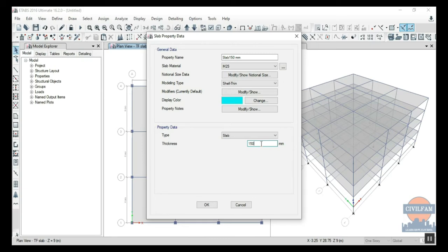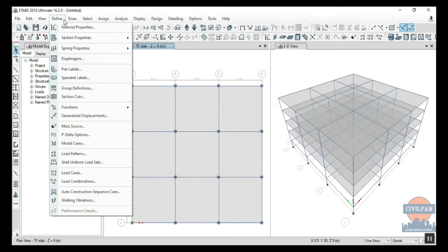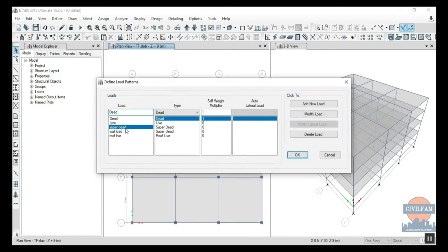All right, we have got some plastering work on it, right? Sometimes you put even granite on it. So how do you calculate all that load? I'll show you in the next model how to do all that. That load, floor finish and ceiling plaster we call it. That load comes under this super dead. We apply floor finish and ceiling plaster.